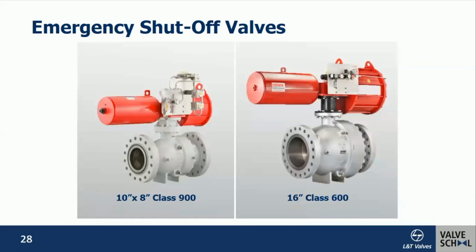I will just go through some of the pictures of these ball valves. It is an emergency shut-off valve, where these valves are provided with pneumatic fail-safe spring return actuators. Although I have classified it as a shut-off valve here, it could also be a blow-down valve depending on the configuration of the actuator selected, so that it could be for fast closing and emergency applications. So these are primarily the shutdown and blowdown applications.